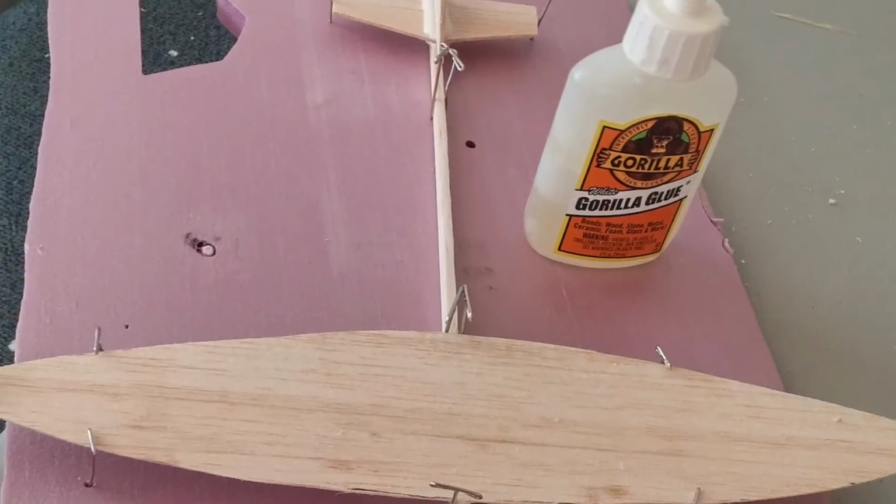All right, Connor, what have you done for this project? Okay, so I specifically worked with the assembly of planes and seeing what you could do when you were assembling the planes to get the best results out of them. One of the very first things we looked at was glue, because we knew that we were dealing with middle schoolers, specifically 8th graders, and we didn't know if it'd be a smart idea for them to use the glue we used, which was a really fast drying CA glue. So we looked at Elmer's glue and 24-hour drying wood glue, and both of those worked okay, but the time it took for them to dry was too long for us. We didn't want to have to wait a day after gluing our planes. So we stuck with the CA glue, but it works fine for the kids to use either.